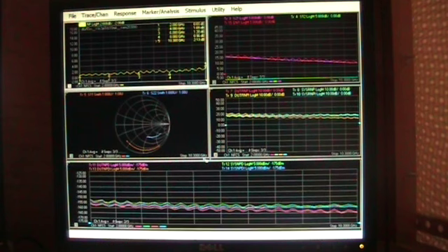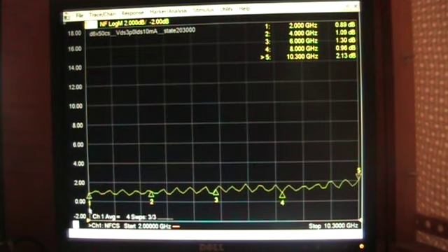In this position we have somewhat of a reflection coefficient, probably about 0.2. We would have to look it up. But what you see here is a ripple in the noise figure. This is because at one particular frequency we happen to be close to F-min, but then as we rotate our way around the Smith chart, we get farther and farther away from F-min.